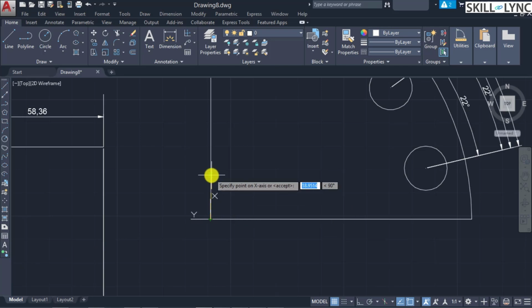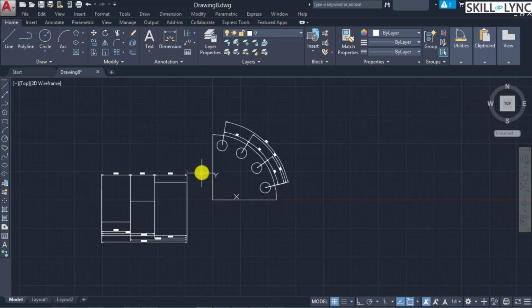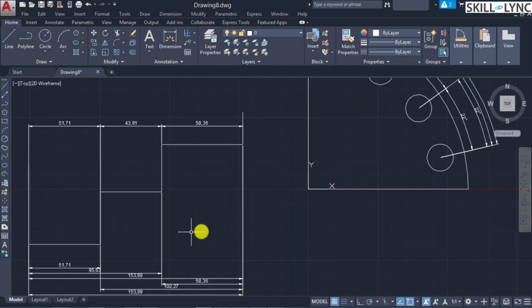So once we fix it, then it also asks for the rotation or the intercept of the x-axis. So we can click on enter or select the point on the same line to retain it. Now you can see that the coordinate system has disappeared from here and has moved on to here. So typically if you refer some datum plane here, it will go in the negative direction because this is on this quadrant. So now having said that, we have moved the UCS coordinate.